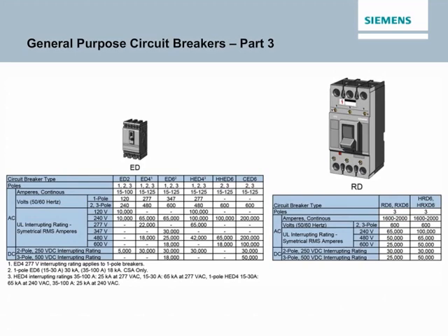Type ED, FD, JD, LD, LMD, MD, ND, PD, and RD thermomagnetic circuit breakers provide a range of frame sizes from 125 amp frame ED circuit breakers to 2000 amp frame RD circuit breakers. For simplicity, the accompanying graphic shows only the smallest and largest frame sizes. Each of these types has variations that are indicated by an H or HH prefix to indicate a high interrupting rating or a C prefix to indicate a fuseless current limiting circuit breaker.